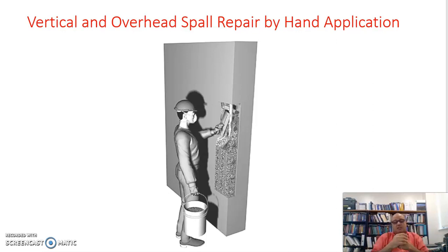Even when I took the students on a field trip to Gate Precast, some of the precast elements that had been fabricated had minor damage at the end, and you use this kind of hand application repair so that you can get this up to the bar, basically up to the expectations for a final product. So you're using the sponges, the wood floats, or the steel trowel, and you can have the desired finish that you want for that mortar.